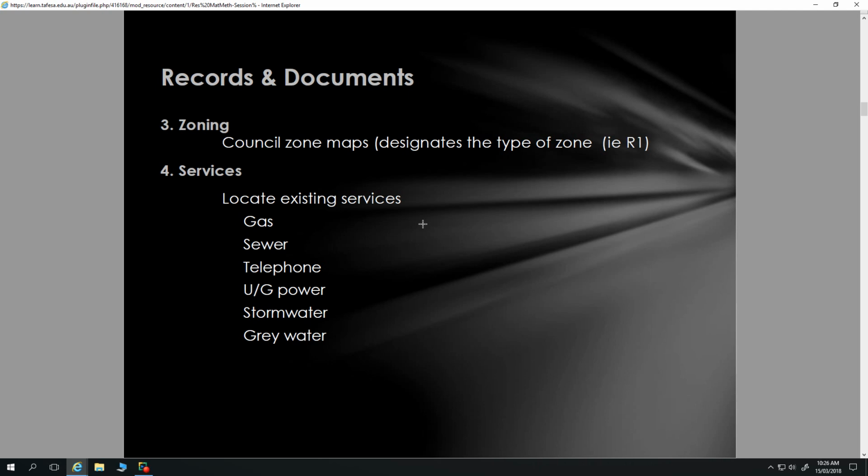It took a little bit to work out exactly what this easement was for, but it was the scenario whereby an allotment had been carved off the back of an existing property, a property in the hills, and the existing property had a header tank up on that portion of land, and so they wanted that head pressure for their water, so they pump up to that, like from the bore, and then that header tank supplies them with pressurised water without them having to run a pump.